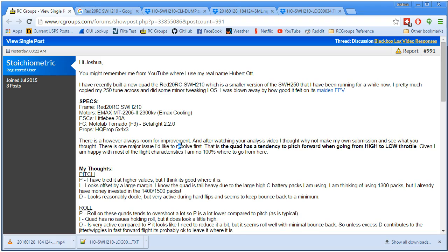Okay, anyway. So what do you do to your PID loop to fix this issue? Number one, as always, you want the P term doing as much work as it can. The I term is slow. It's slow and steady. If you rely on the I term, you will have a very unresponsive copter. We need to make the P gain as high as it can be on pitch without introducing bad effects. And then we bring up the I term to a level where we feel like the problem is handled.